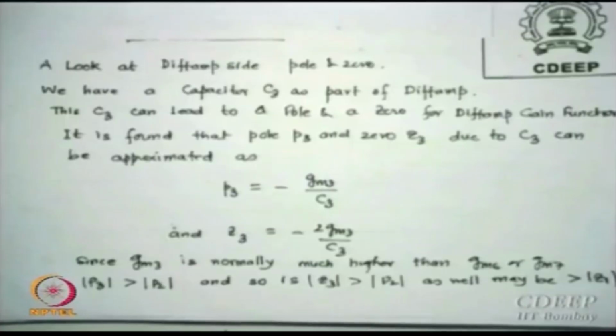So this is important, because we keep talking about how we create a right half plane 0 or shift it to a left half plane 0: we need a resistance. So next time when we design, we will try to see somewhere instead of C it should be R and C in series, and once we get it, much of this 0 on the right hand side can also be handled by us. That is the next stage which we will have to do. Right now I assume that without anything, 60 degrees phase margin is achievable with whatever values I choose, but in case there is an issue further, I may actually start looking at the 0 also.